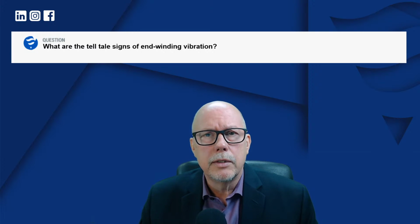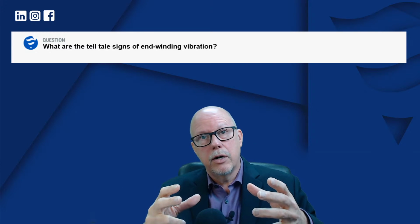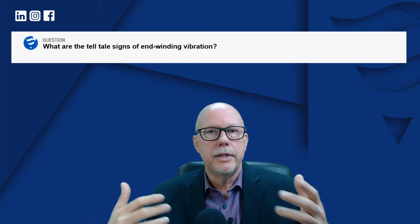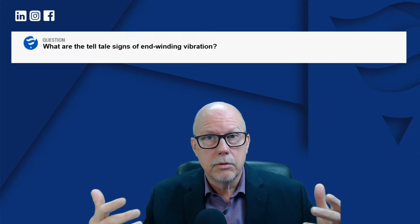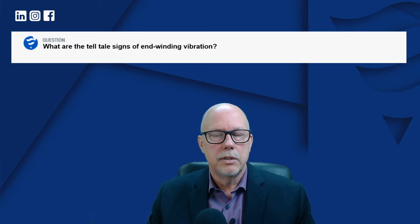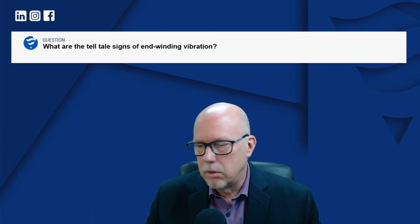Finally, if you go in the unit during an outage and you see clear evidence of damage, ties that are half broken or completely broken off, support blocks that are dislodged or missing, on the floor, ties the same thing, on the floor, cracking of the insulation, all of these are telltale signs that you have a vibration issue. With water cooled units, you'll have the water box or the cooling conduits leaking. That's another clear sign of a vibration issue. So all of these during the visual inspection, when you stop the unit for an outage, are clear signs of vibration. And there are clear steps to be taken to try to resolve these issues.